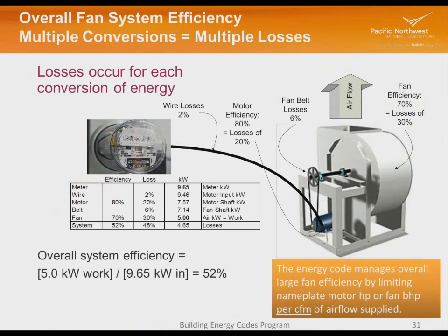What goes on in a fan? Well, the purpose of a fan is to move airflow. So we have an air horsepower we're trying to achieve with this fan, related to how many CFM we want to move and what the static pressure is in the ductwork. The higher the static pressure, the more work it takes to move that air through all that ductwork. So the smaller the ductwork is, the more work it's going to take to move the same amount of air.